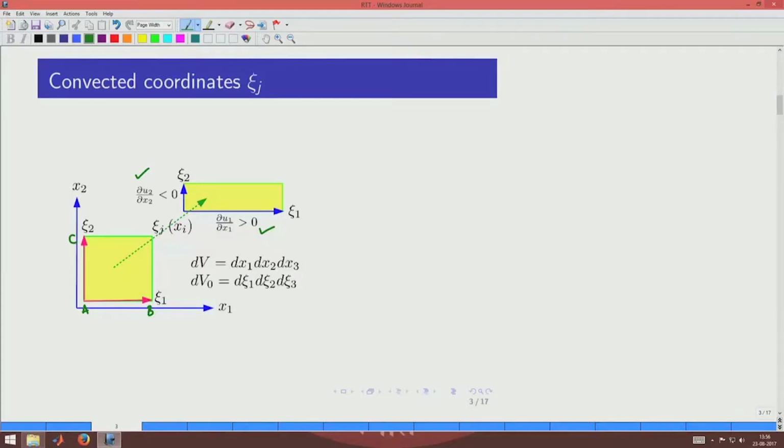Now, what we are doing is that we want to define the volume of the fluid element using the spatial coordinates x1, x2, x3 like this. Because the spatial coordinates we are always taking as orthogonal, we can take it as a triple product of the vectors dx1, dx2, dx3, and then we can already see that the product is directly giving us the volume of a volume element in the spatial coordinates.